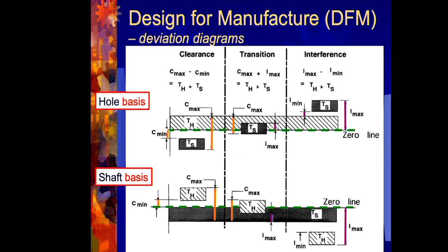So the zero line, if I was just talking about 10 millimetres, well, the zero line would be 10. And given that that solid line is going below 10, minimum diameter 9.9, 9.8. 9.9 up to 10. No greater than 10, or else the manufactured component is outside of the design tolerance. It fails the design tolerance test. So holes, shafts, and all we're looking at now are those little tolerance zones.